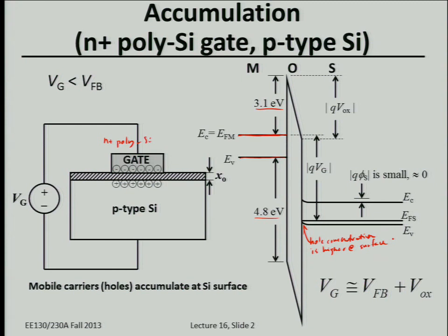So the total amount of energy band bending in the silicon really can't be too much. It's not very large. Typically, the dopant concentration in silicon nowadays is like 10^17, 10^18, so the Fermi level deep in the silicon is already close to the valence band edge. There's really not much room for the energy bands to bend in the silicon.